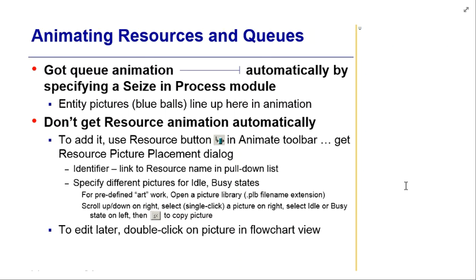I mentioned this earlier. When you're doing a simulation and you're running it fairly slow, and you're trying to understand what's happening within that simulation, changing the entity color and/or type based on what's happened to it, what loop it's going through, for example, what happened to it in a Decide module. Has it been told to go to a specific process? Whatever it is, to sort of show that change.